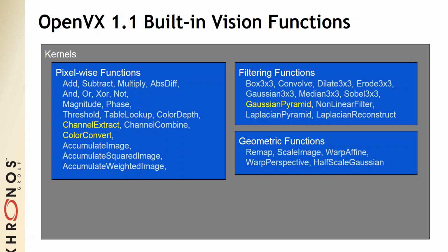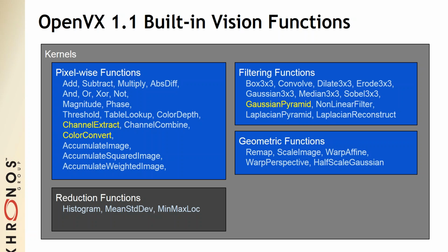And there is remap, where if you don't have a standard mapping, if you have a very nonlinear complex way of mapping input to an output, you could use remap. You can compute a table offline and then pass that to the remap node, and the remap node will just perform that remapping operation for you.